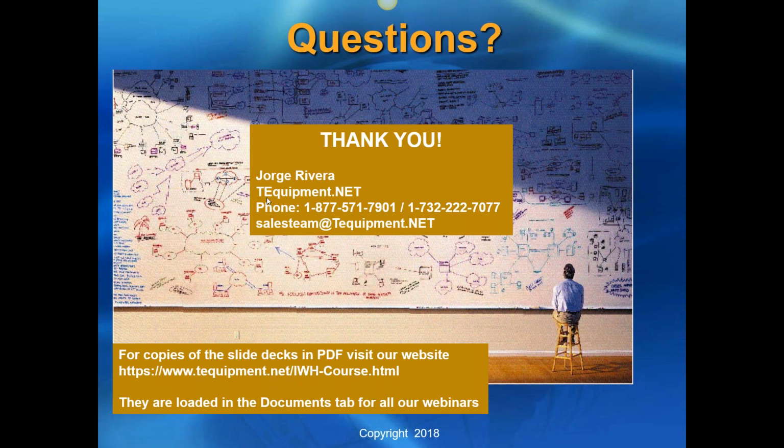Well, we've got two major documenting calibrators, the 729 and the 754. I'll talk about those real quick. The 729 is specifically a pressure calibrator. That's all it does, and it does it really well because it's got a built-in pump, a built-in reservoir, and a built-in controller, so it automatically does pressure calibrations. It's got HART, and it can communicate with our DPC Track 2 software, or ProCal V5, the enterprise versions. The 754 is multifunction.